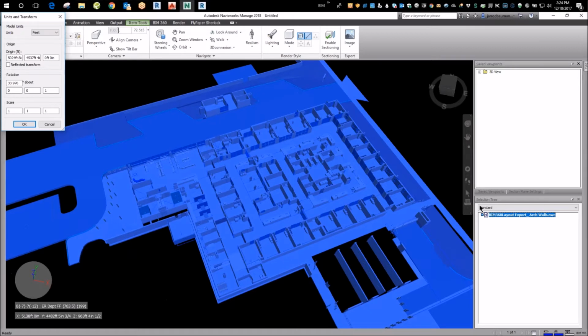So there's a foot unit. That's what civil engineers use. Architects use inches. When you type 1, it's going to go an inch and treat that as an inch, right? If you needed to go a foot, you'd have to type 12 inches. So it's important that when you're working, normally everything's in inches, right? When we're in the building, all our clash models, all inches, pretty much.